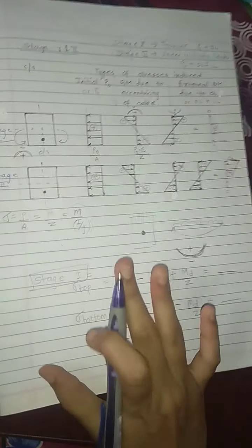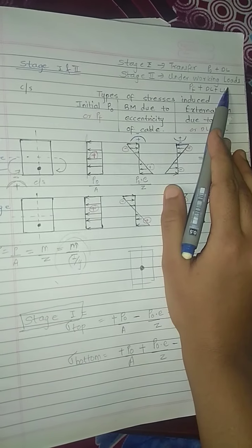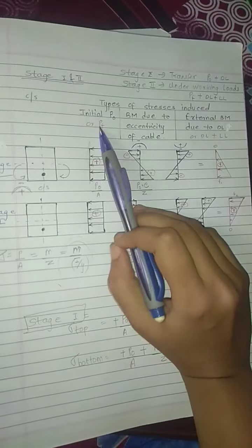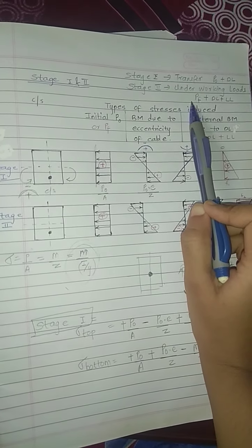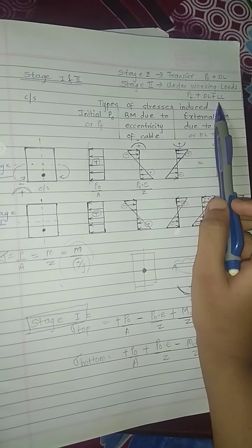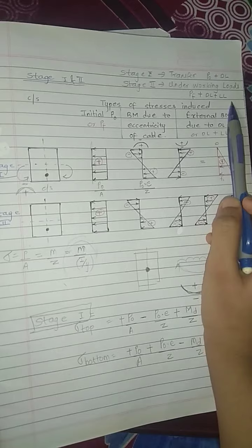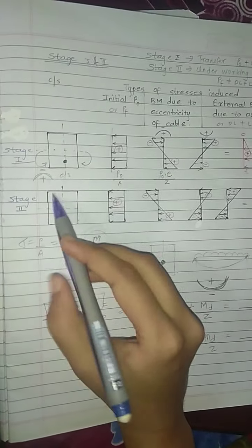Okay. Now let's look into stage 2, which is under working load. Now here 2 parameters change. First is the initial pre-stressing force with some losses. Here the final pre-stressing force is taken into consideration. And one more thing is that under live load, the live load factor also we have to consider. So same at stage 2,